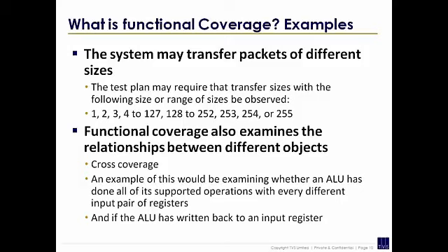So it will tell you at the end that you've now generated all of these packet sizes. Okay? So that's now told you that you've done what your test plan said you needed to do. Your test plan is saying, write all these packet sizes. So within a VHDL test bench, you probably write a test for each packet size, and you write those tests and off you go.